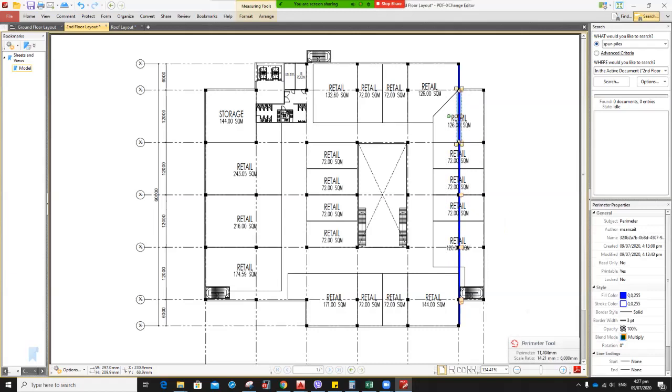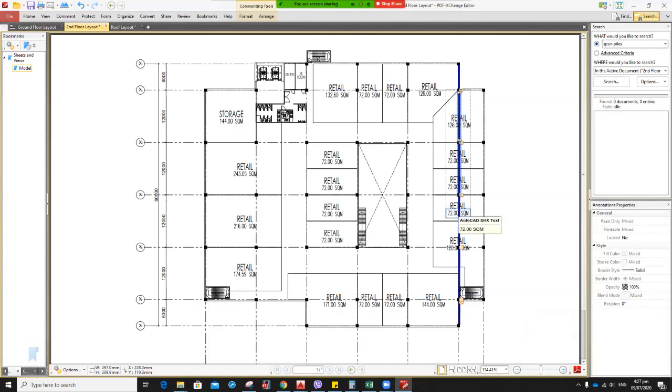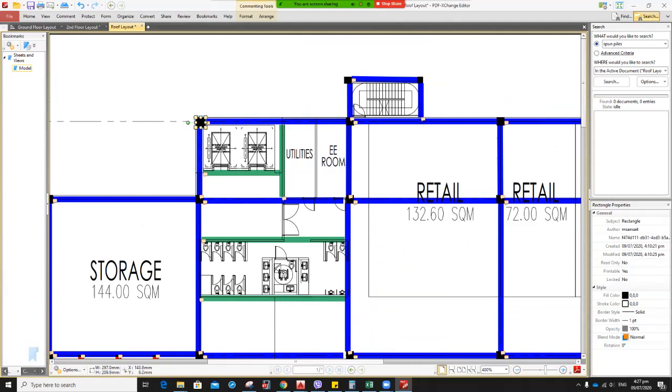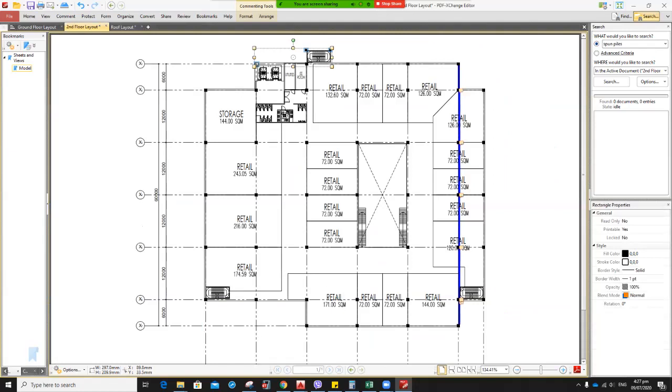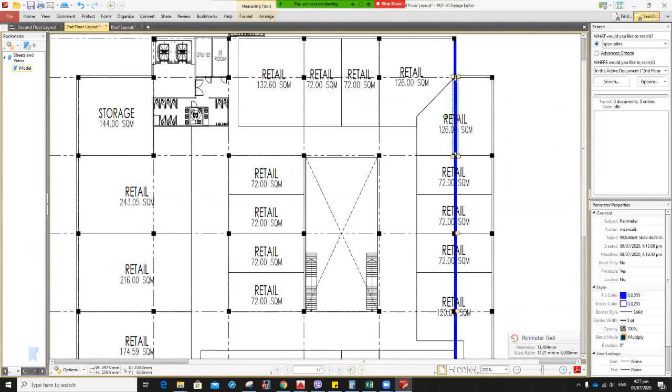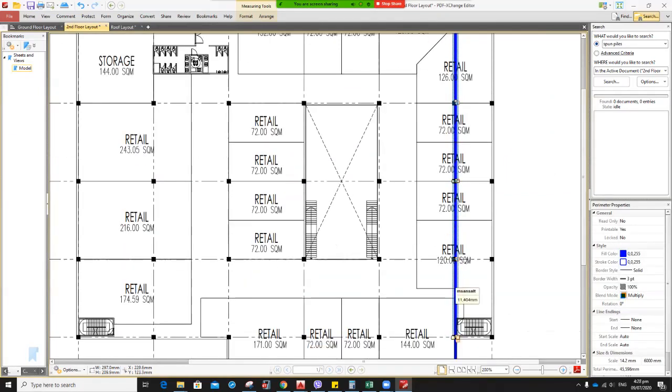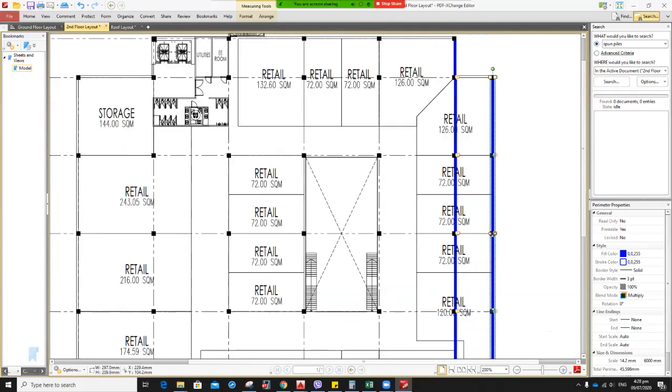Okay, so let's start the second floor. We will project here the framing. Copy. Okay, so first we need to copy the columns that we planted. It's important to put it here. Okay, good thing it coincides. Then we need to copy this one, the girder, so we can distribute the girders. Okay, so from the edge.